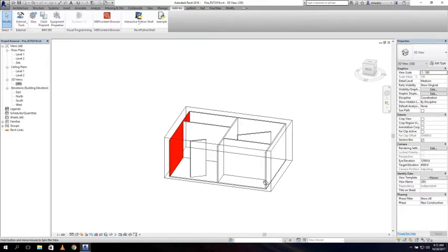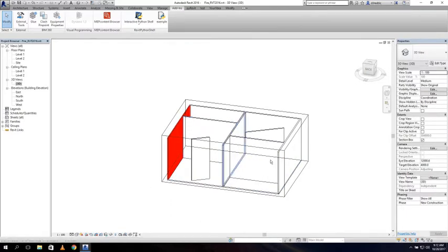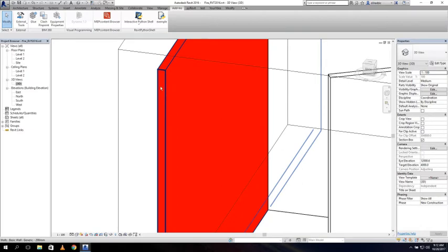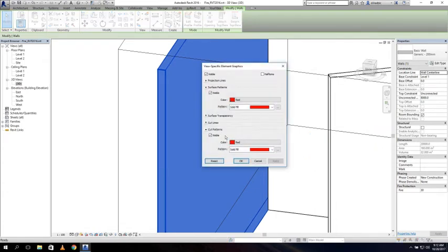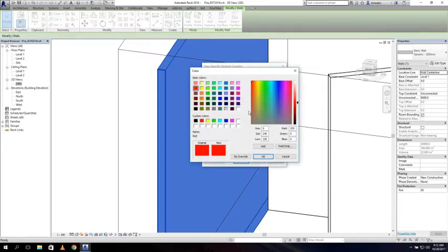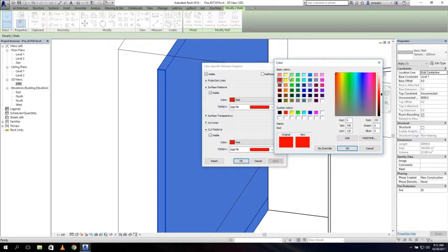And at the end of the video we made a Python script, and it will override the whole model with the colors, but it will also override the cut pattern. I just showed you how you can do it in Revit, but in Dynamo you have a node, and it doesn't override the cut pattern. So if I go to by element, the cut pattern, in Dynamo there is a node, but it doesn't allow you to override this option.